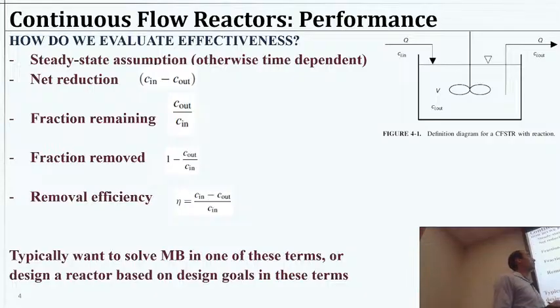Of course, we can change that if we need, in which case our outcome is going to have some time dependency, right? So if I have a CSTR with something flowing in it, but over time what I'm feeding it is changing, that could mean we're not at steady state. Or we just initially started up a reactor. Let's imagine a scenario where we are starting a wastewater system, but we don't have a stable bacterial colony yet to do the consumption.